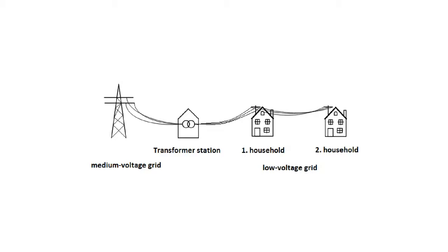A typical problem is the risk of overvoltage in a low-voltage strand due to the power supply of private photovoltaic systems in the course of a day. A low-voltage strand consists of many homes and a transformer with a fixed turns ratio, which connects the strand with the medium voltage level. All components are connected parallel to each other to function independently.